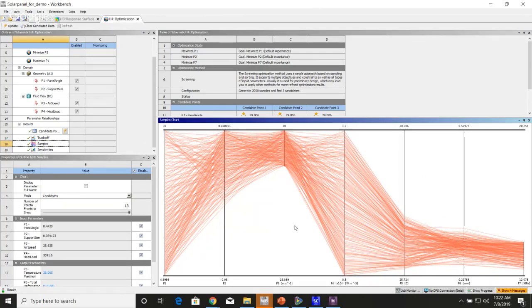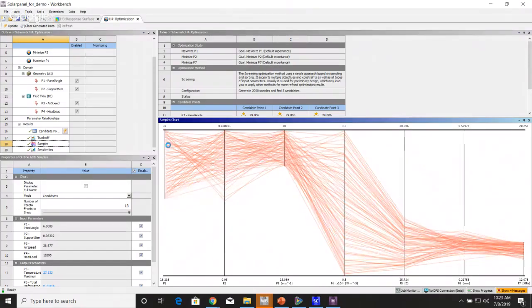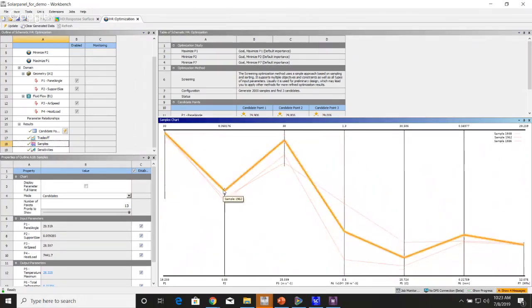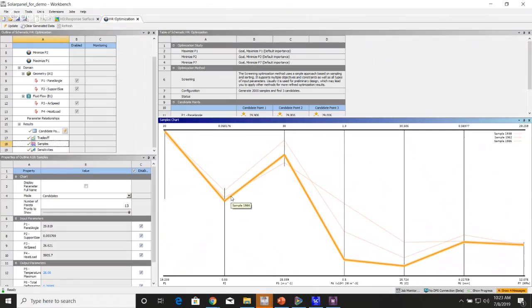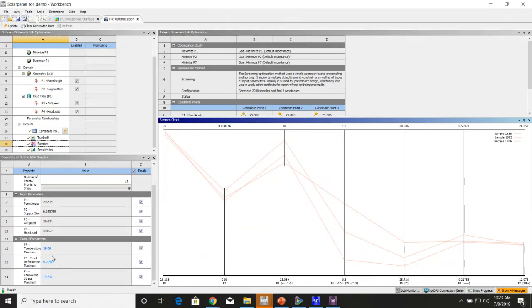Next, typically we want to reduce the cost of our structure, so we want a fairly small member size. Well, we also want to be able to withstand a fairly high angle. So let's reduce the member size of the design, and now we're left with a few designs here, and we can use this as our trade-off. So one option is, this particular design is a 30-degree angle, and it's at a 26 meter per second airspeed. It's able to meet our stress and deformation requirements.